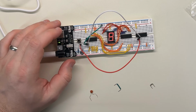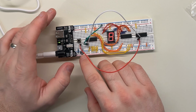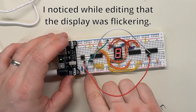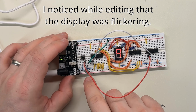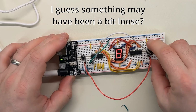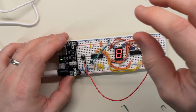So it takes roughly 100 milliseconds for the capacitor to fill up to, I think, 60% or something like that. So that means that when I first turn it on, because of the way this is hooked up, the capacitor immediately starts to fill up, and it takes about 100 milliseconds to get high enough to trigger the Schmitt trigger, which in turn causes it to invert the signal here.